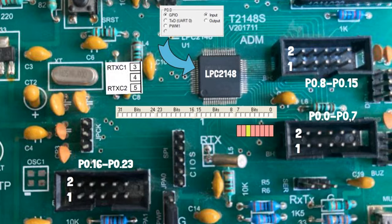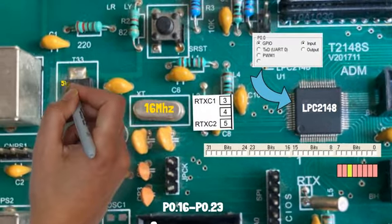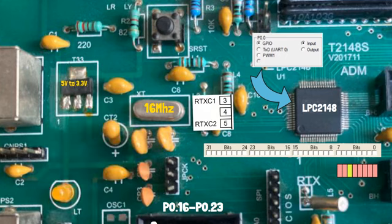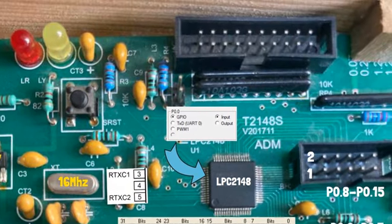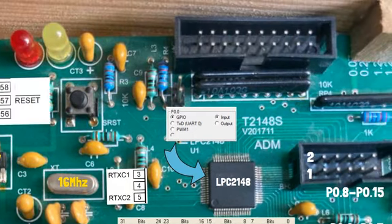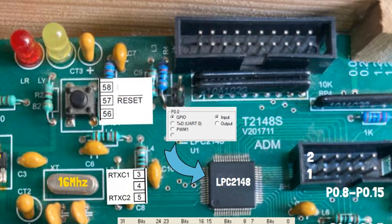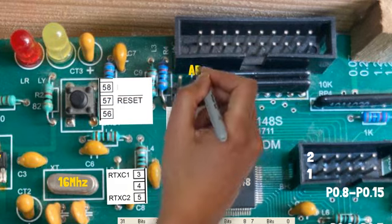LPC supports a crystal oscillator up to 30 MHz; a 16 MHz oscillator is wired to this demo board. A 5-volt dropout regulator provides 3.3 volt power to LPC 2148. A switch is connected to LPC 2148 reset pin number 57. A low on pin 57 causes the processor to begin execution at address 0.